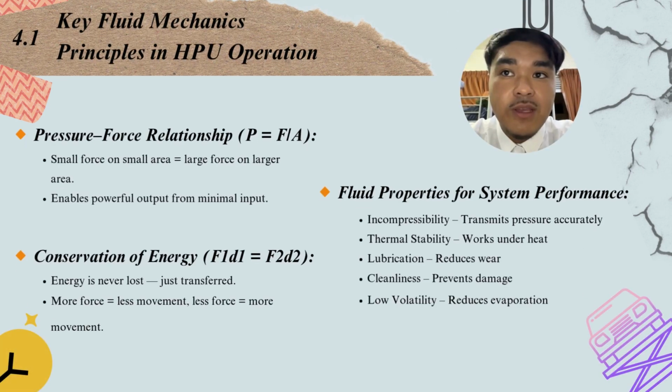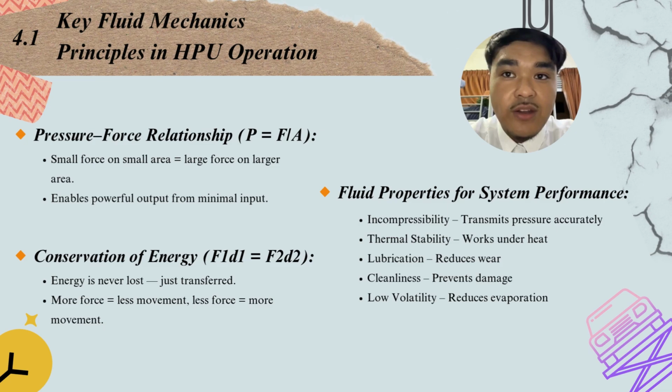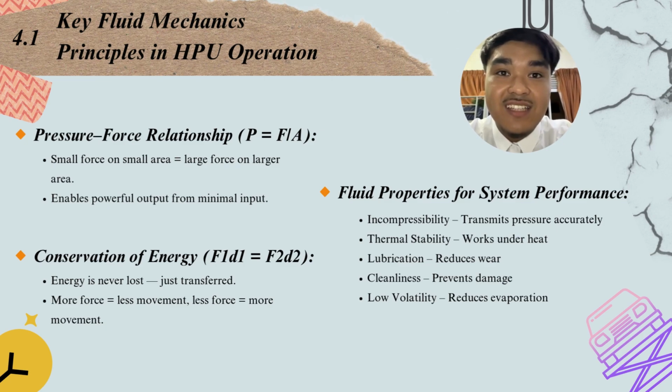4.1 Key fluid mechanics principles in HPU operation. Pressure-force relationship, which is P equals force over area, where a small force on a small area is equal to a large force on a larger area, and it enables powerful output from minimal input. Next key principle is conservation of energy, where F1 D1 equals F2 D2, where energy is never lost. It is just transferred, and more force means less movement, and less force means more movement.